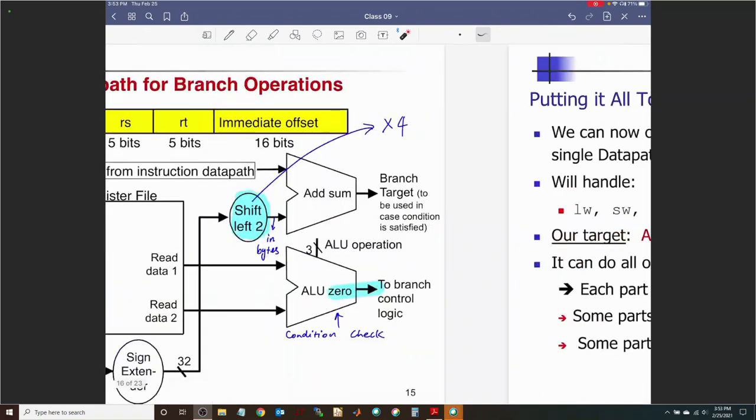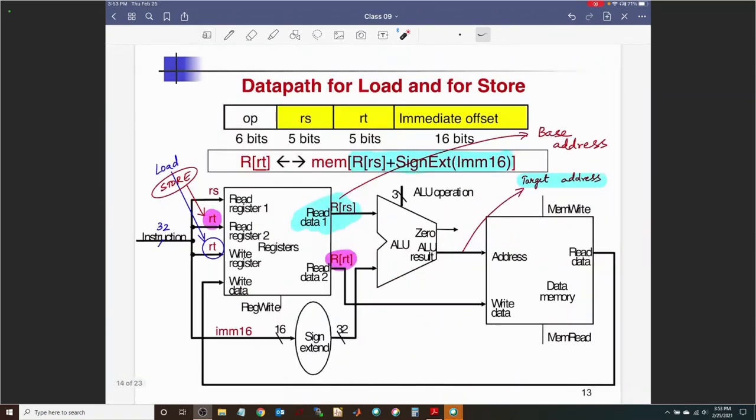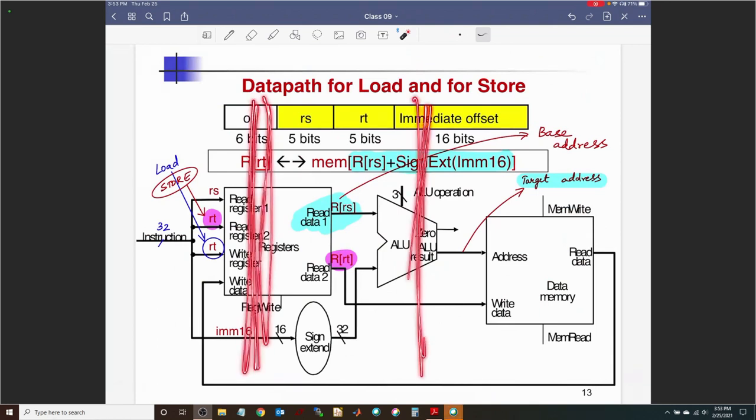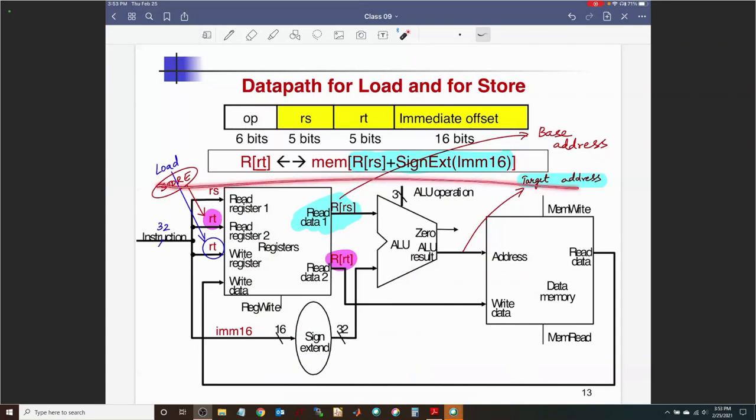If you think about this, you see over here, there is one stage of register file, one stage for ALU, and one stage for memory access. What I'm trying to do is look at one instruction going through the entire cycle, as opposed to one instruction being in this particular step while another instruction is using that hardware. I don't want to do any pipelining here just yet.